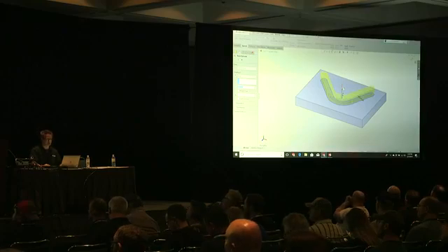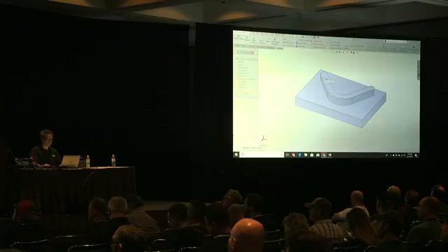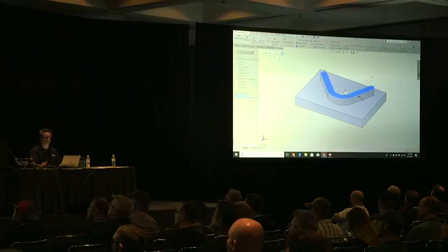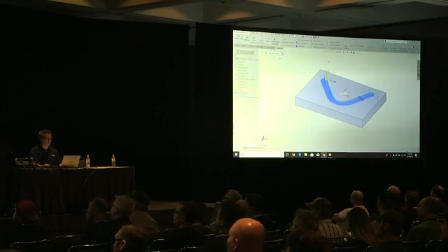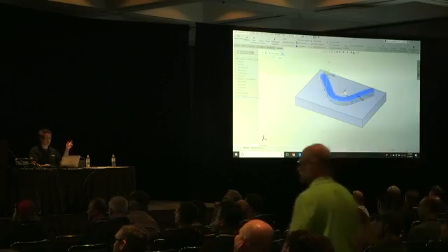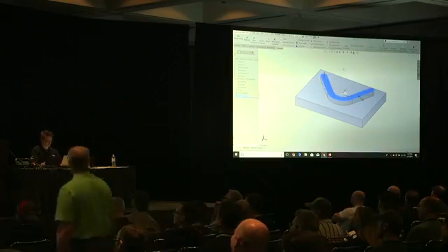Paying attention to your pointer. There's my mouse. Right-click, confirms it. Here's a little bit of trivia for you. It's kind of one of those forgotten things. I have 2 bosses. Is there a good way to convert a boss into a cut? Yeah. Grab the arrow. It's a cut, it's a boss, it's a cut, it's a boss. That's the way to do it.